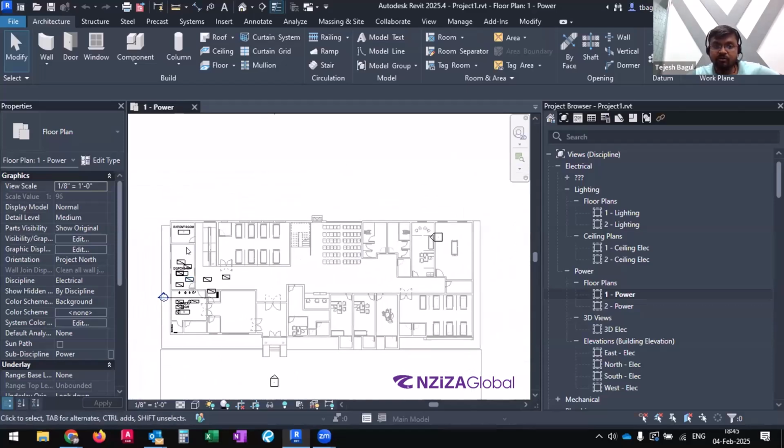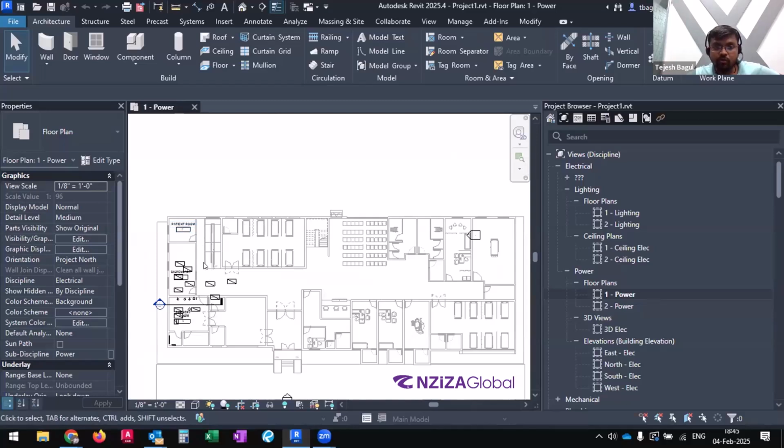So in this case, the path of exit, let's say for this patient room, will go all the way from this point to this point, the nearest exit. All right, and the building codes will usually ask us to make sure that the minimum foot candle is supplied when there is a power failure. In case the occupants of the room want to exit from the room, we want a certain given minimum foot candle level or lux level. Again, this is dependent on the building code of a given country or a given geographical area. So always make sure that you have that properly modeled.